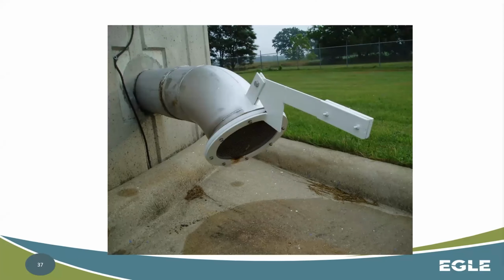Here is just an overflow. Now, the biggest thing I want to point out about these, because we're going to talk about these over the next couple of slides, is although, yes, that's good. It has a nice concrete pad here, so it can overflow. It'll be great during the summer. You have a screen, although the screen maybe looks a little large. Ideally we wouldn't want that 24 mesh screen. But the biggest concern here, especially if you're in northern Michigan where you're going to have cold weather, is that having an open portion here, not a closed flap all the way around, might create a chimney effect.